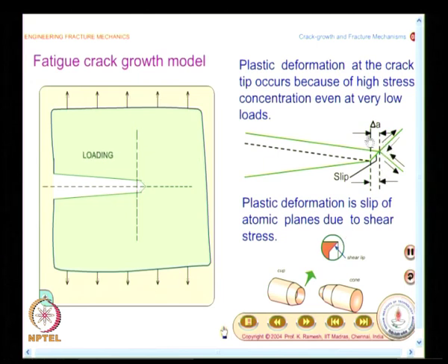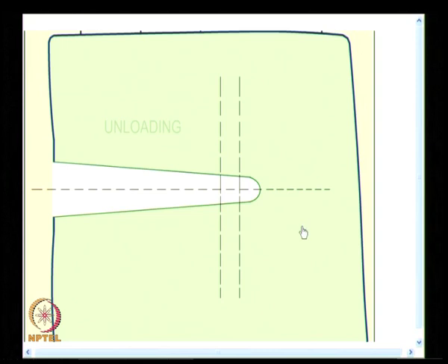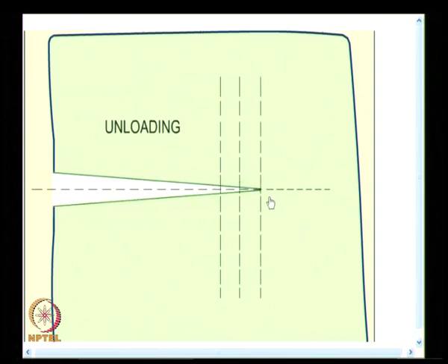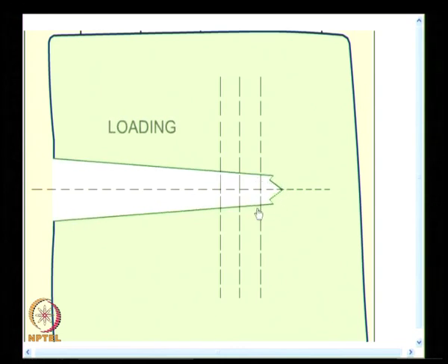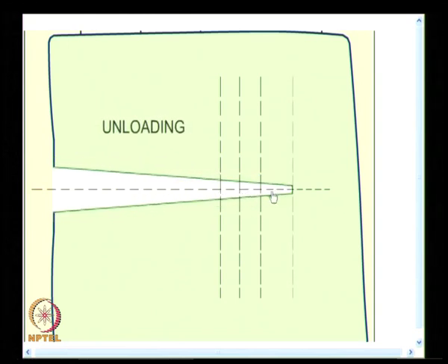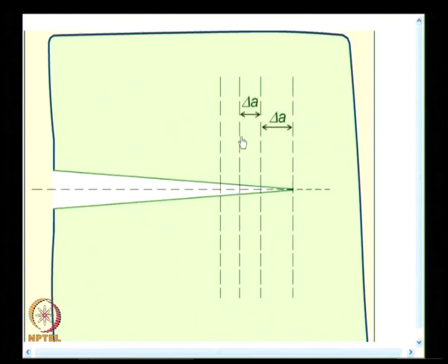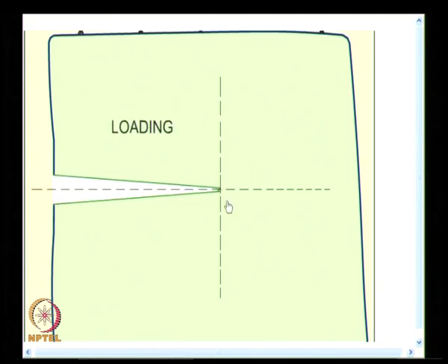What you will have to keep in mind is all this happens at a microscopic scale. It is very highly enlarged for conceptual appreciation. So, when I have a crack, I have a slip that takes place, and we have a model of how a fatigue crack grows as an animation, and this is purely done based on the kind of processes that are involved in advancement of the crack. So, here you have a microscopic model bundled with a macroscopic appearance. What you see here happens at a microscopic level. Imagine that you will have 4 or 5 striations in a span of about 2 microns. So, this is sub-micron level, but this is highly magnified. When you see the picture in high magnification, you see the kind of details that you look at.